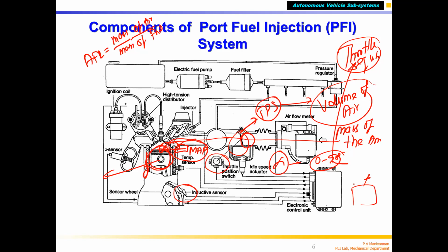But around the value of 30 degrees, 1 bar, say 31 degrees, 1.1 bar, 1.05 bar or 0.99 bar, there is an error. Please note the error. It is acceptable because you are not worried too much. Correct? So that's why you have multiple tables. But multiple tables are too difficult. So you cannot create infinite number of tables for accurate control. But now, if you want Bharat 6 control, correct? Emission norms, if your vehicle has to adapt, it has to be still more accurate. N alpha may not be sufficient. Even Bharat 4 has difficulty, that's why the other method was shown here.